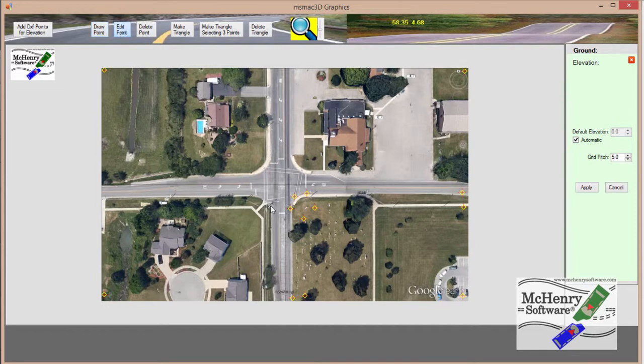Now, next thing we want to do is edit the points. Let's make this -10. Minus in graphics is negative is below the ground, positive is above the ground. In the three-dimensional simulation, it's the opposite, but you'll get used to that. We put -10 for all these. Now I've just set these 5 points on the bottom of the ditch to -10. The rest, everything is 0.